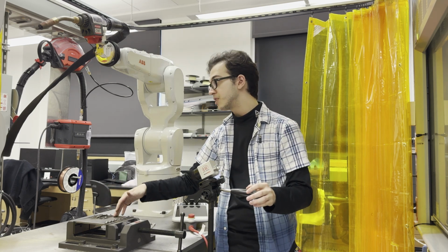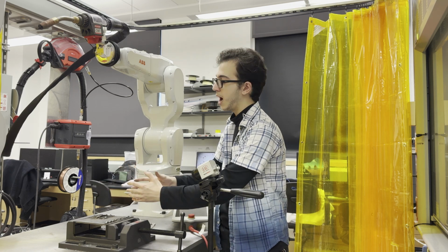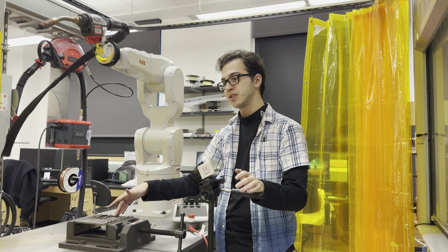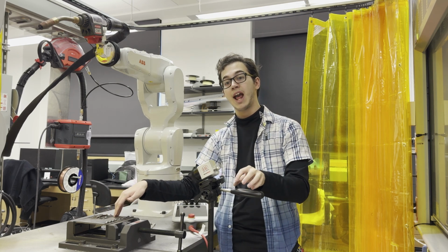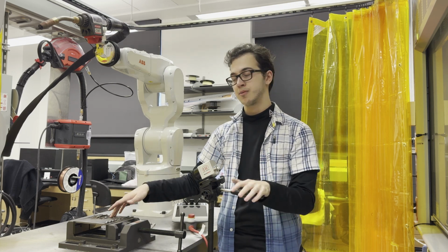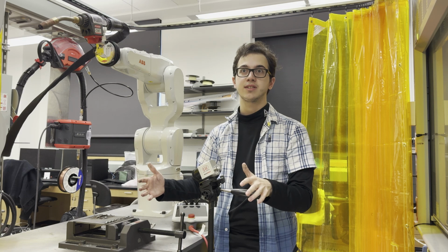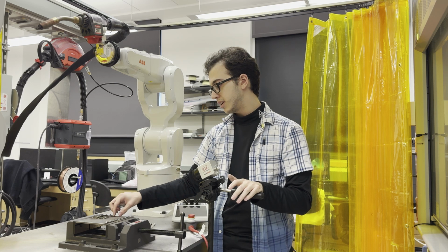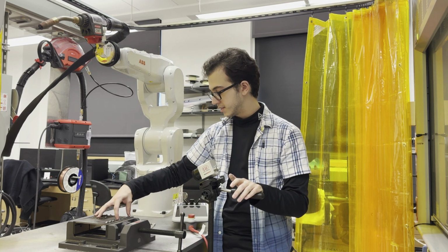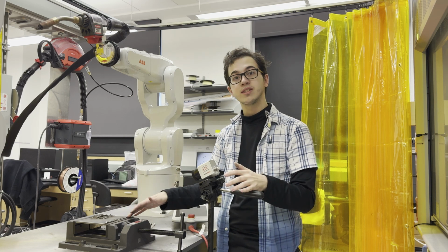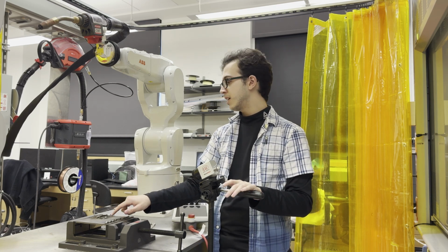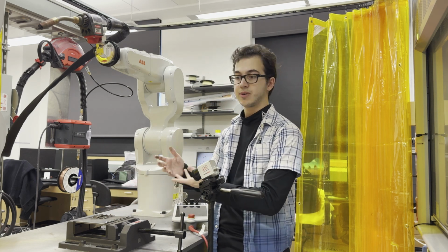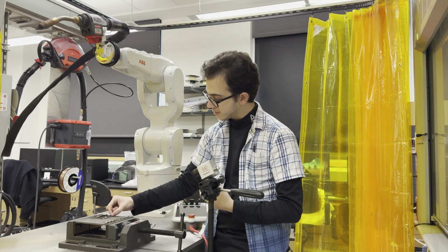And lastly, the movement speed of the robot itself in the sort of XY plane. We found it best to move at 6 to 7 millimeters per second. However, whenever we wanted to create abnormal samples to compare for our machine learning algorithm, we would intentionally run the system at 5 millimeters per second, which would create these larger pockets where the material wasn't depositing appropriately, whereas at 6 to 7, it was moving faster, and in conjunction with the feed rate, the IPM, we get very nice and smooth depositions.